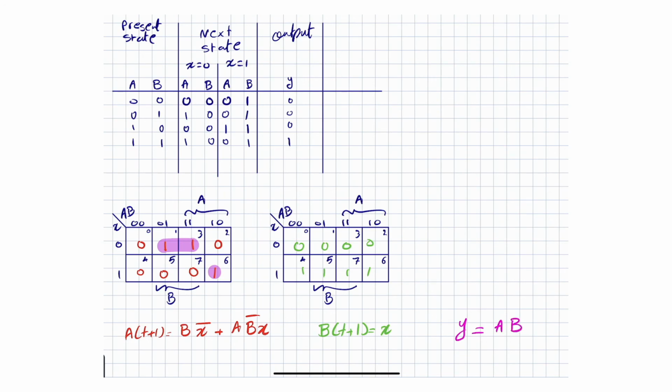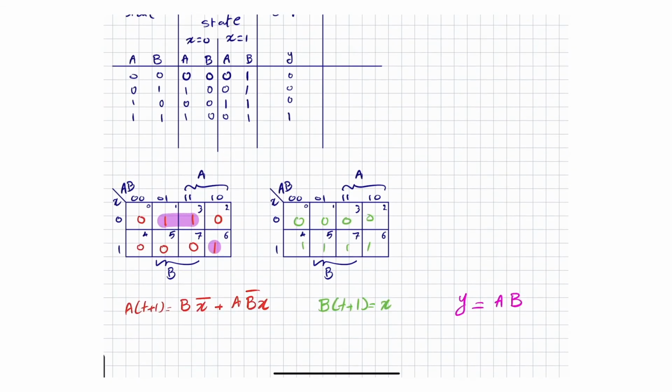So what's the next step? Well, the next step is to draw the circuit in here, and we can figure out how to do it. It's just a flip-flop followed by another flip-flop. I'm going to call this my A, this my B. Of course, these are clocked, so I'm going to write the clocks in here. So what's the value for B? Well, B will just get the X.